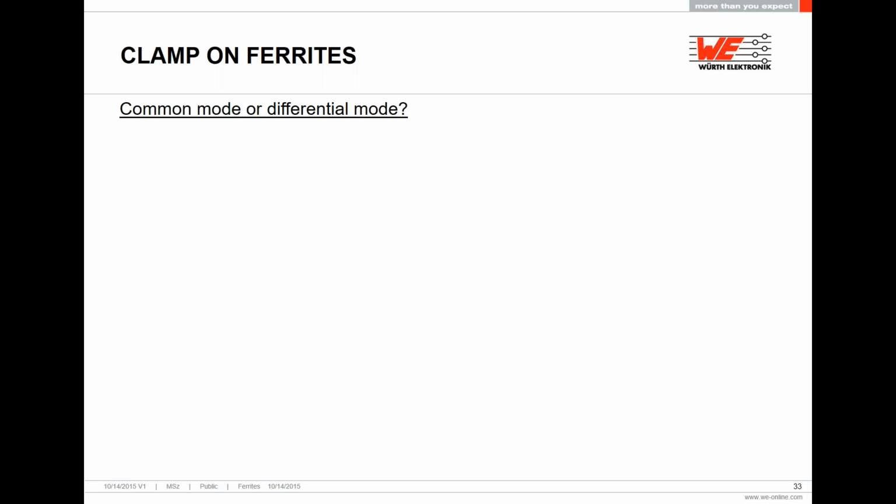To choose the right EMC component, it is very important to identify the noise that you have in your system. First you need to question if you are dealing with common mode noise or differential mode noise. Here's a quick trick to get you heading in the right direction. It is not 100% accurate, but will help you start the process of elimination.